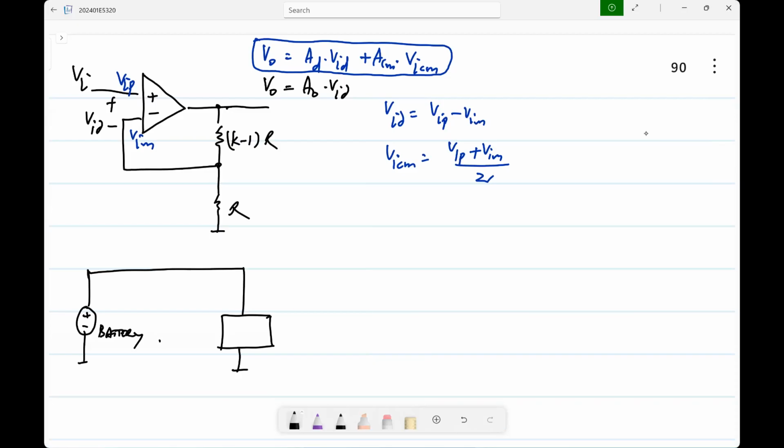So one thing is to measure the current, you have to place something here, in series, wherever the current is flowing. Now, the moment you place it, it will have some drop. If that drop is significant, it is completely wasted power, right? Because just for measurement, you are wasting that power.